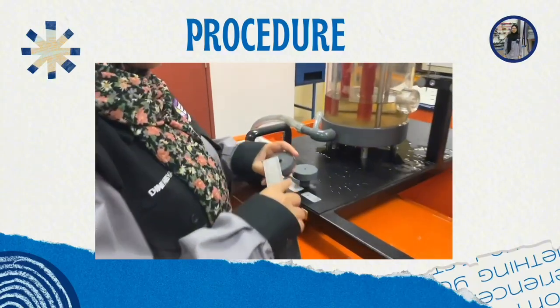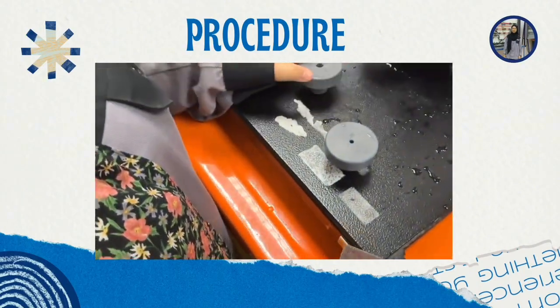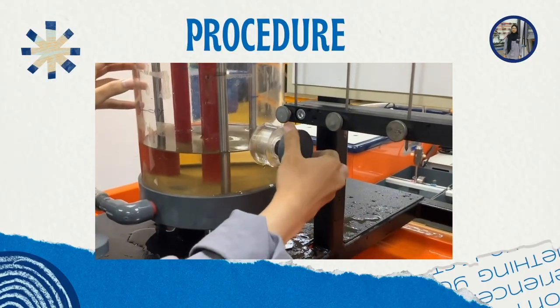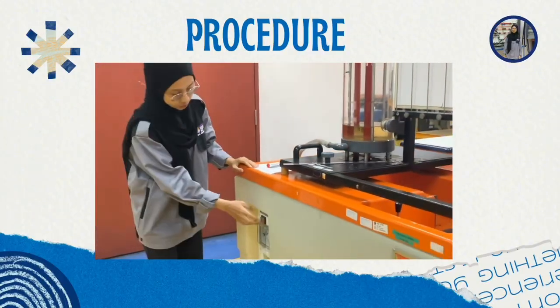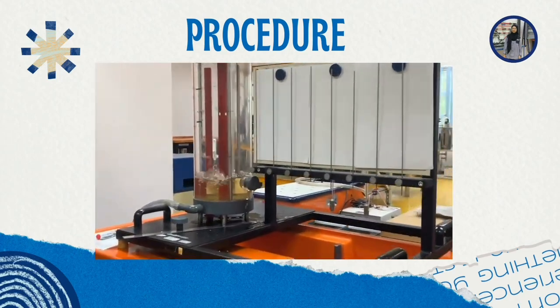Firstly, we measure the diameter of the orifice. The diameters of the orifices are 4 mm and 8 mm. Place the 4 mm diameter orifice at the tip of the reservoir. Next, turn on the hydraulic bench, then adjust the water flow.